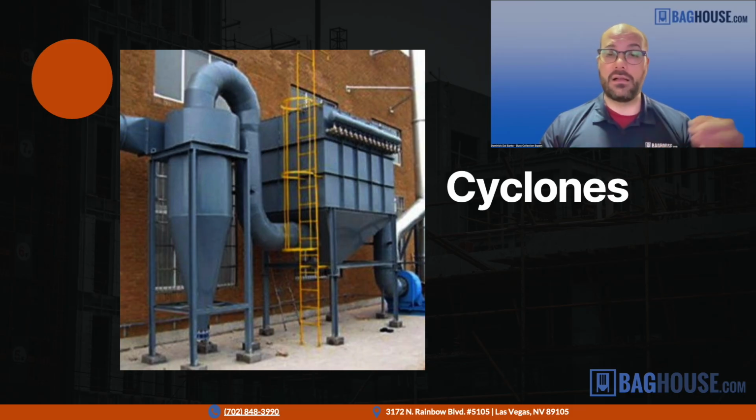And then we bleed off some of the air from the cyclone that has the fines in it, so the material that's gotten smaller than we want, and that goes to the baghouse. It's a very common application or usage for cyclones in the mining and cement industries. So again, good for pre-filters, remove most of the dust, and oftentimes are paired either for some process reason, but often are just used to lighten the load, the dust going to the baghouse.